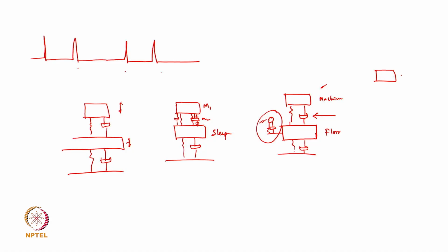Yeah, a tuned mass damper is also used in another case: you have your machine, and on top of the machine people can also put it, then the machine itself will not oscillate directly, the damper will oscillate, so the base itself will be very, very quiet.